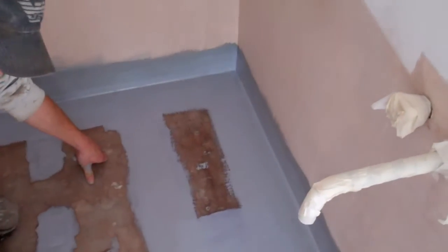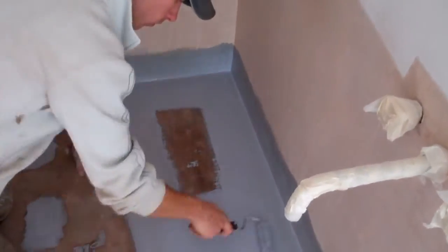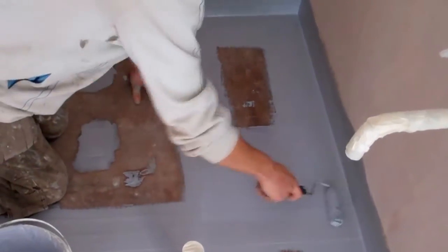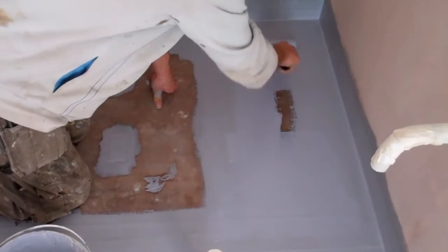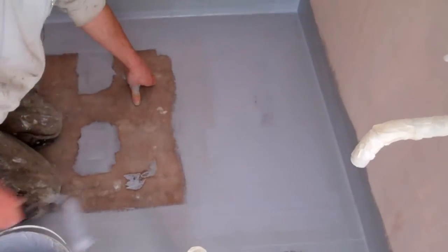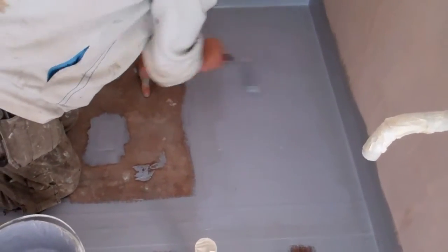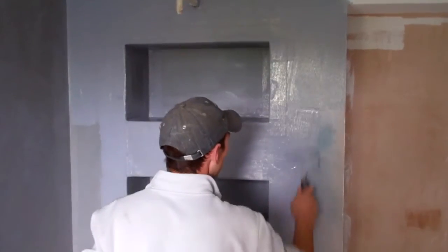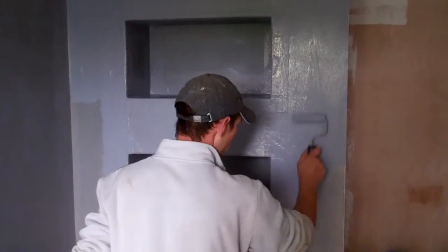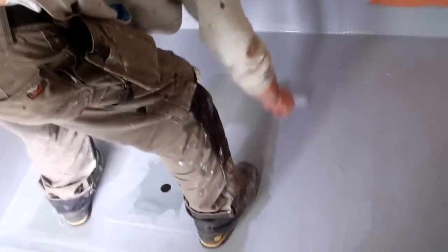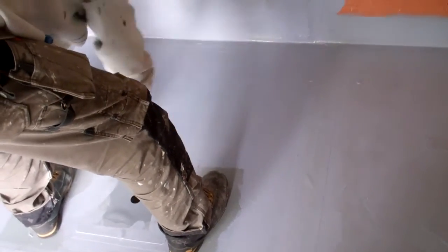Now all the detailing is finished, we can apply the first full coat of aquaproof compound. For this we recommend the use of a short nap fur roller. Use the roller to gently roll out the aquaproof onto the walls and floor without spreading the material too thinly. The aquaproof is applied at a total thickness of approximately 1 mm. This is normally achieved in 2 coats, each ½ mm thick.